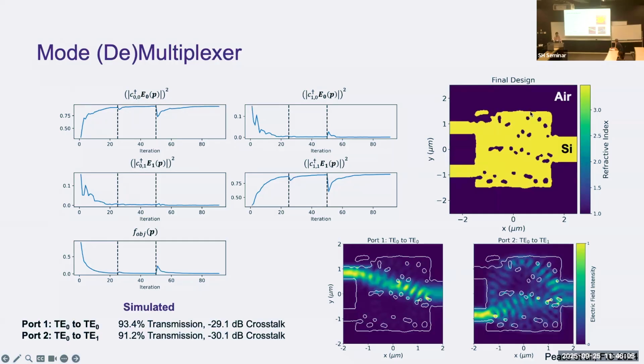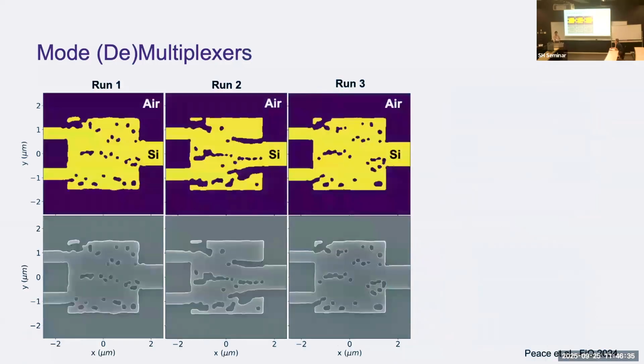We simulate it. SPINS has its own simulation of the modes as well. We use Tidy3D these days. Do you know Tidy3D? It's a really good FDTD, really good. So with Tidy3D, you don't need to make your own FDTD, use Tidy3D. It's got a nice graphic interface as well. So we simulate the device, we see that it works.